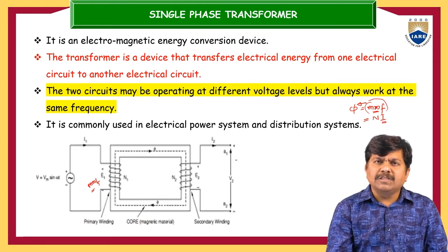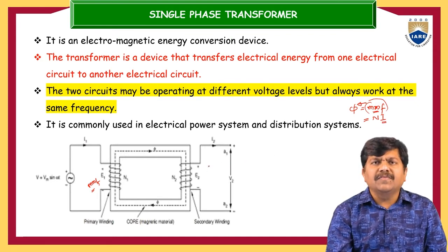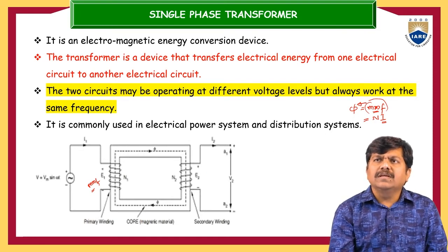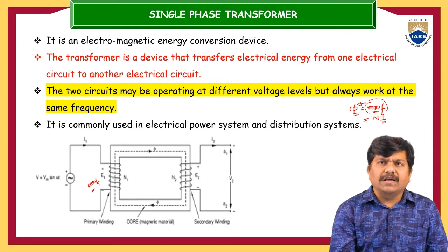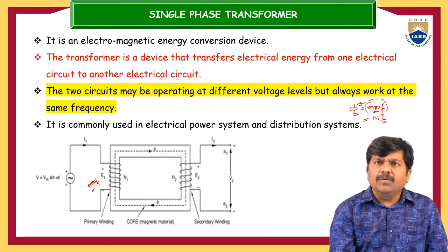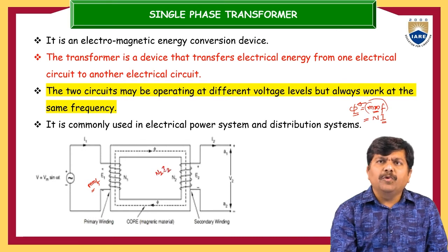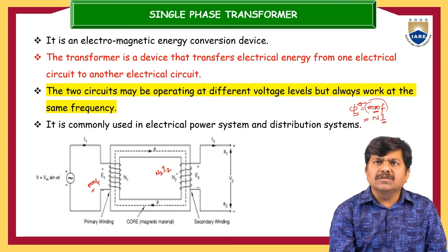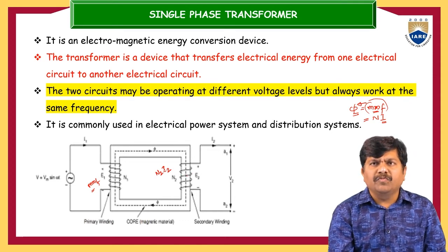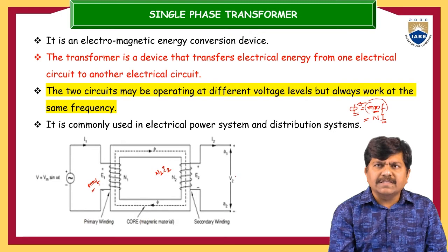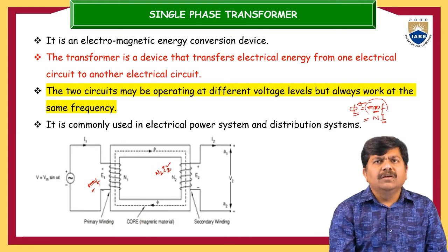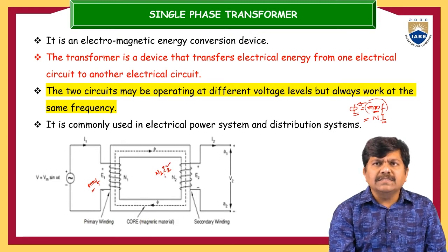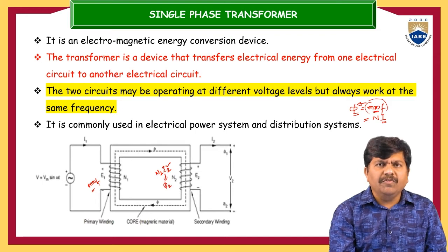Now, please try to remember this particular point, as it will come up again in the forthcoming videos. This magnetomotive force is capable of driving some amount of magnetic flux. Similarly, across the secondary winding also there may be some magnetomotive force, N2 I2, with I2 driven through N2 number of turns. Suppose once this load is connected, I2 comes into the picture. I2 is also capable of driving some amount of flux lines.